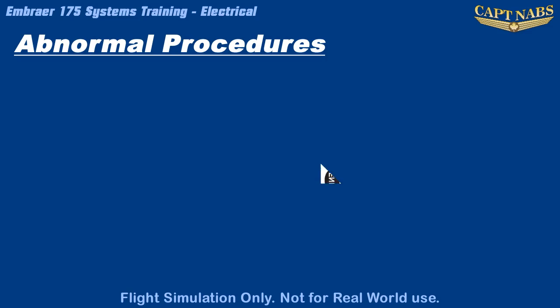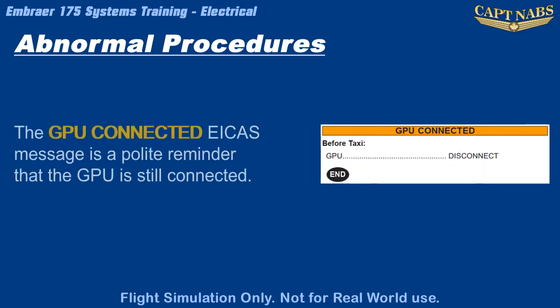The GPU connected ICAS message only appears if the parking brake is released while the GPU is still powering the aircraft. Ensure the GPU is disconnected prior to taxi.